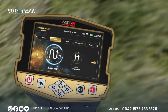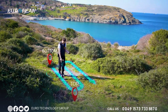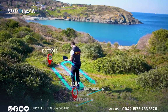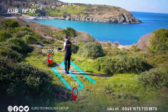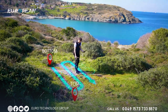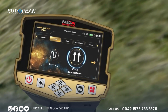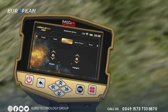2. Zigzag. In this case, the start of the next scan line is at the end of the previous scan line, while leaving an offset distance, meaning that every two successive lines are scanned in an opposite direction. Select your preferred scan path mode using the left-right arrow buttons, then press the OK button.